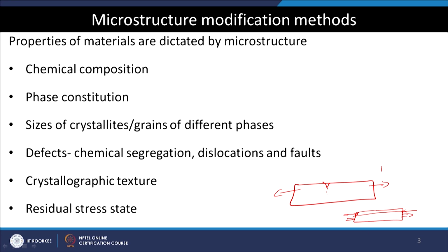And then, in the case of the same defect, to progress it requires a higher effective load. That means this P will be more than this P. So, that is how one can control the failures in components by engineering the residual stress.